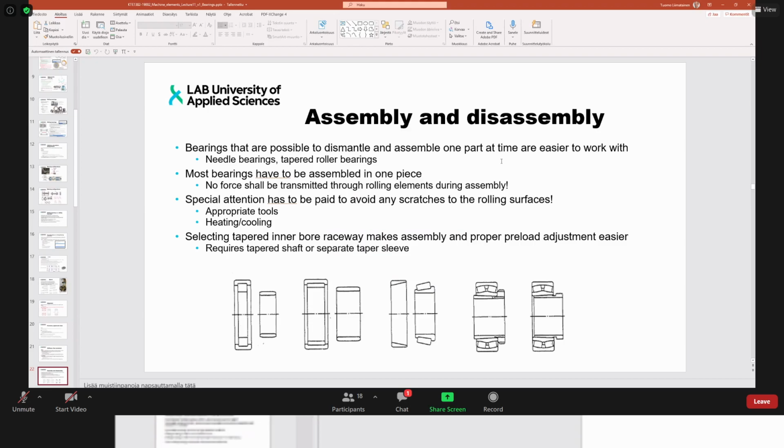Yes, it can. It's been also in my background while we were producing electric motors. It happened that there was some improper handling or improper assembly, which caused very, very small dents in the raceway, something that we didn't find or see in our own testing when the machine was tested after assembly, but they were there. And when the machine went to the customer and they ran it, for example, 1 or 2 years, these small damages evolve into a major bearing damage.